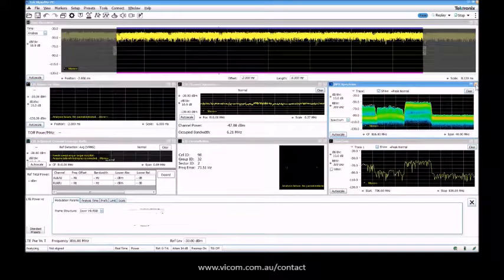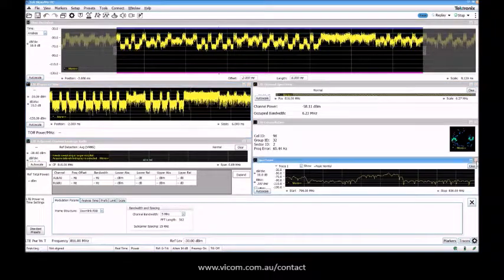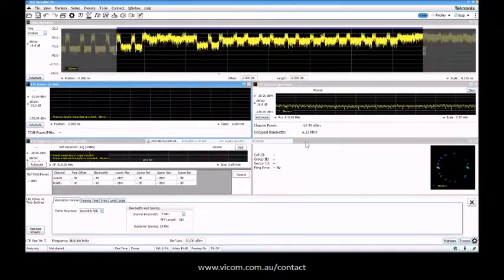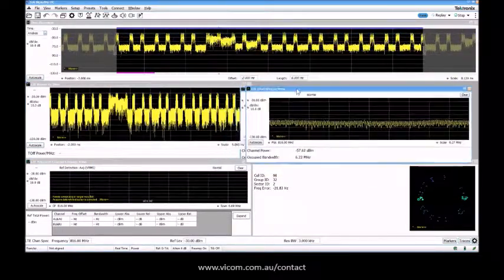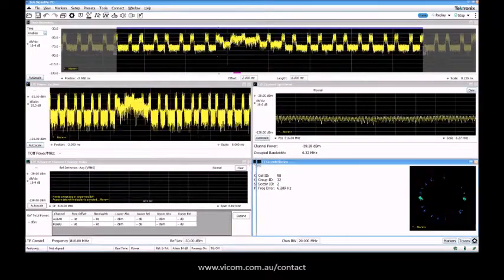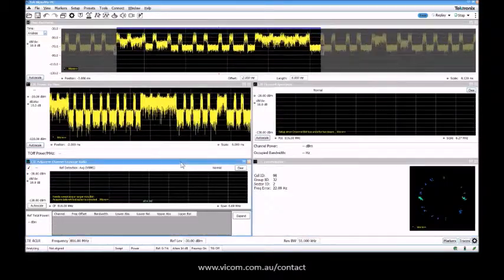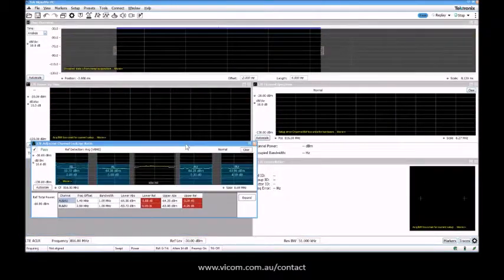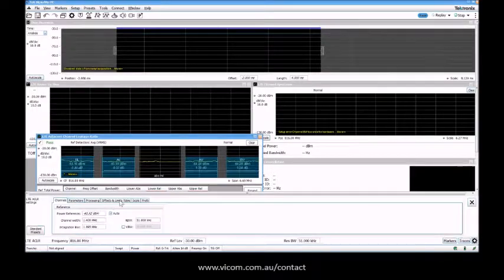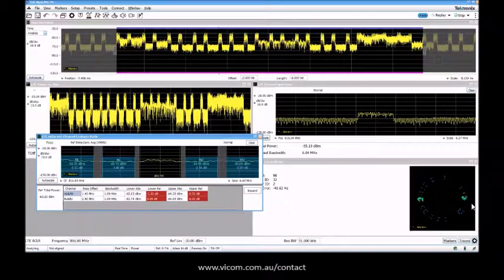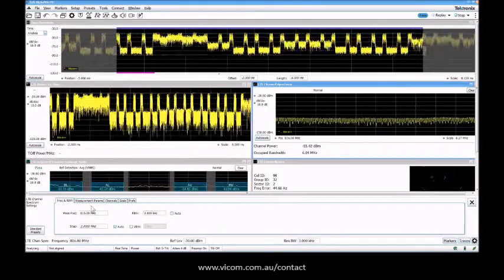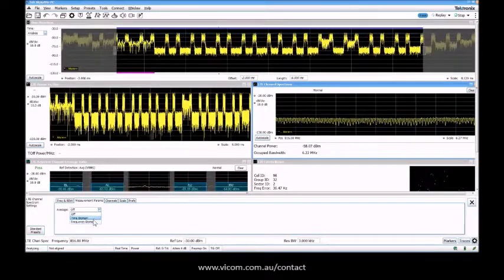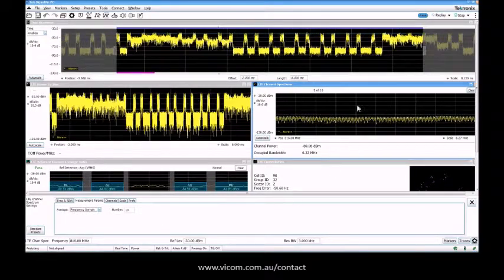This one, the real time, we can close. We really don't need that one. We really don't need a spectrum. And if you end up with something like this, you always have the possibility to move this around and make them a little bit smaller. So in this case, we have swept here, and this one. I just need to check that so we can do it real time, like this. And now I'm checking most of it. This spectrum here, I'd like to see it as a measurement parameter, and it should be frequency domain averaging. So if we have any burst here, we see it.